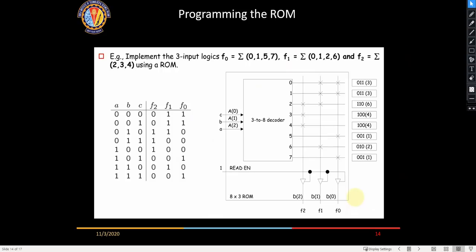So the connection with the read enable and the data lines are tri-state buffers, right? Yeah, they're tri-state buffers. Any reason why they're used over an AND gate? Yeah, a tri-state buffer is much easier to implement at the transistor level, right? That's why they have used it.